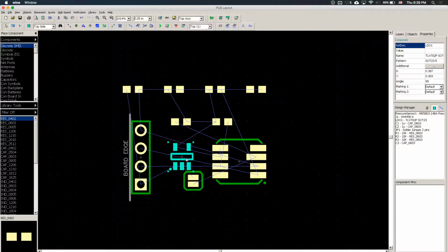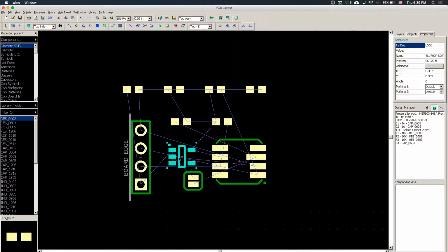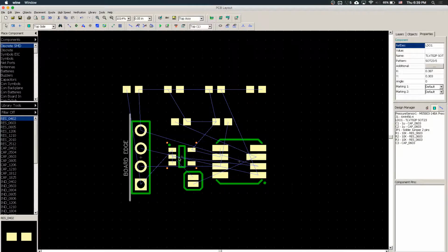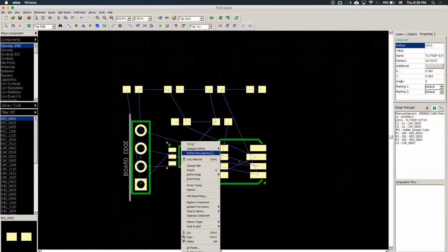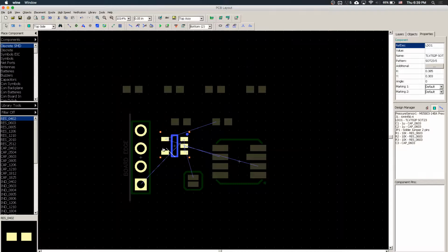So you can drag a component very easily just to place them, and you can rotate the component by itself to put them into different orientation. Usually there's 2 layers of PCB, so you can press B to go to the bottom layer and T to go to the top layer. And to put the component onto a different layer, you right click on it and you click change side, so that will put it into the bottom layer of the PCB.